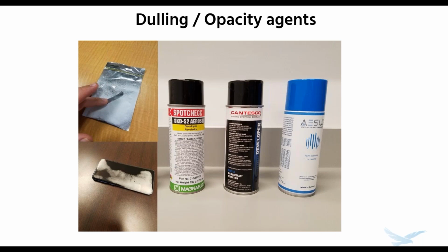So there are workarounds, but in general, lasers are best for thin edges, and they're also best for shiny stuff. And blue lasers specifically are the best all around. Otherwise, you're going to be using talc. There's not much out there that scans chrome.